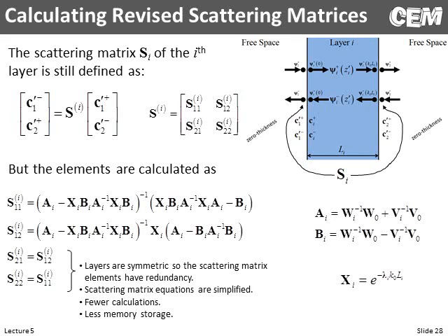So we've doubled our speed. We've made this very versatile because we can change the order of layers however we want to. We're doing fewer calculations, less memory, and our S parameters are consistent with convention. So for all those reasons I argue the way we're doing scattering matrices in this class, which is different than how anybody else is doing it, is much better. They're much more useful, simpler, and more versatile, and we can change the order of all the different layers if we want to.